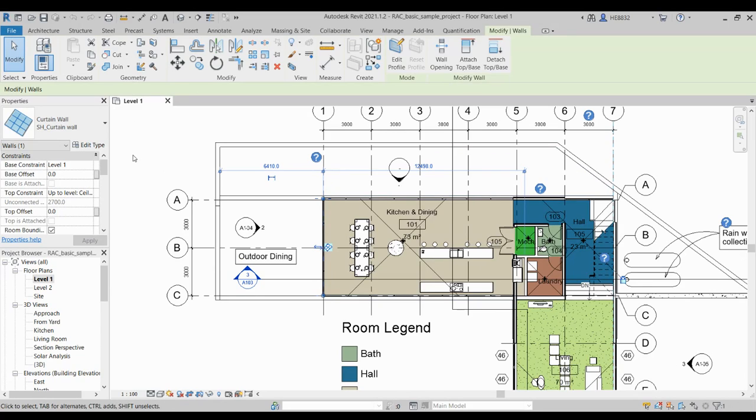We first just went over how to open files and we started to name some of the details about the quick access toolbar at the top, which, if you remember, is customizable. If you hover over any of the other icons down below on the main ribbon and right click on them, like I have just done, you'll see that it says add to quick access toolbar, and then you can just click on that and it would populate in the list above up here.